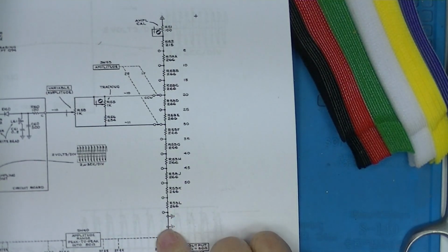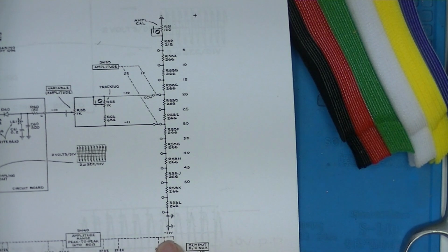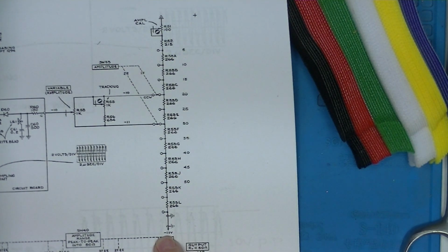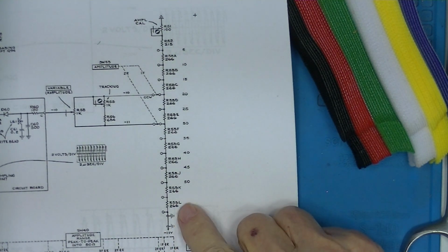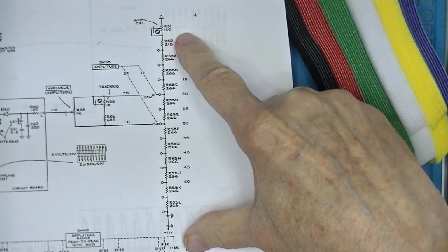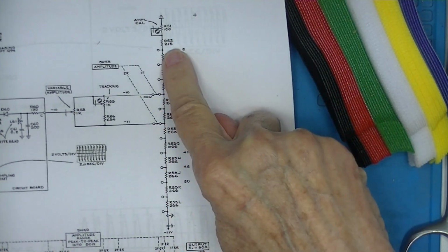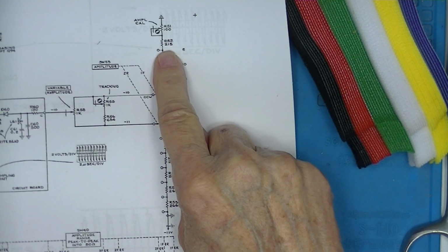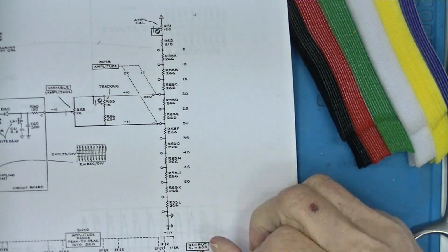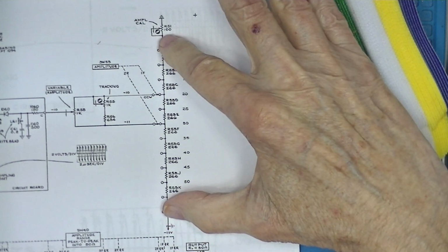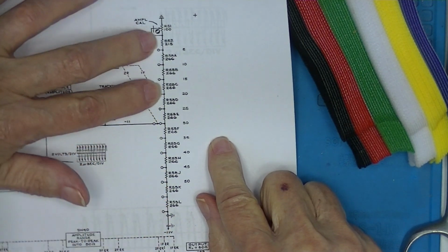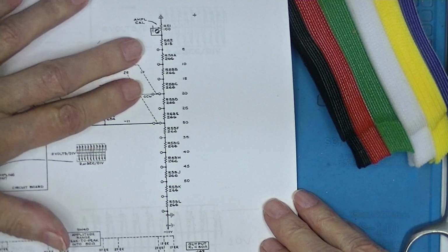So look at this interesting string of resistors here. This end is grounded. This end is supplied with minus 11 volts. They have a string of 266 ohm resistors from here to here. And then we have a 215 in series with a 0 to 100 potentiometer. We have a 10 position switch that rides up and down. Here it is here. This 10 position switch